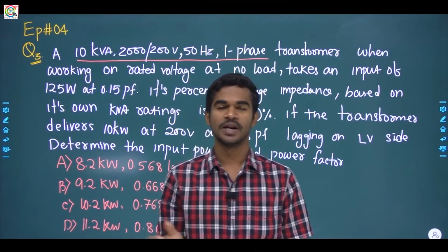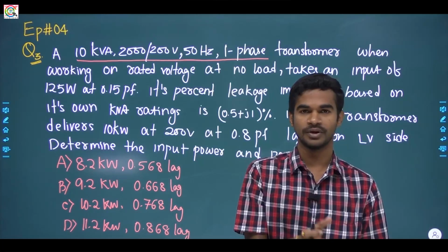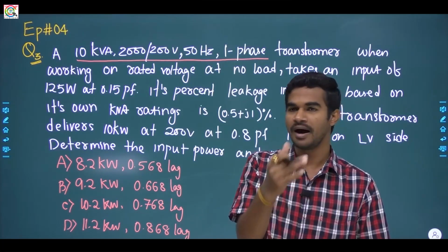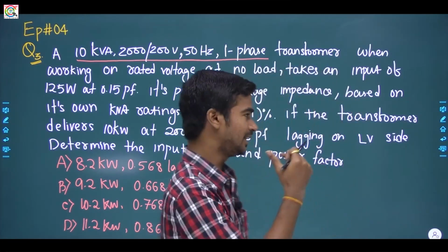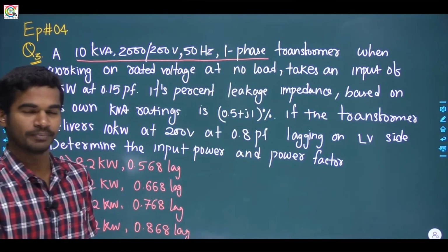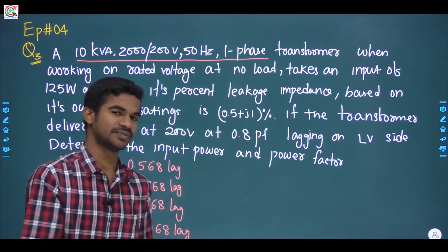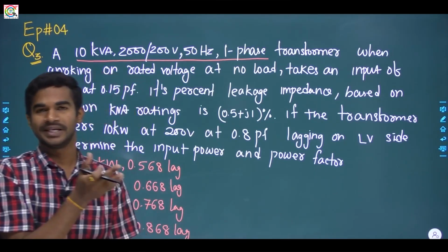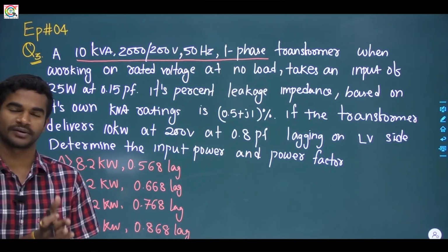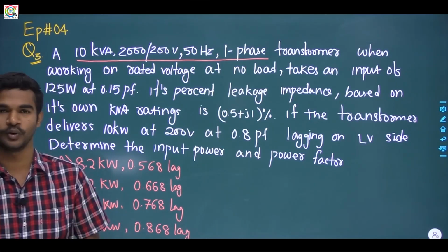Its meaning is that the no load test is performed on the transformer, that too on the HV side. Whether the test is performed on the LV side or the HV side, we will get the same amount of losses, that is the iron losses.